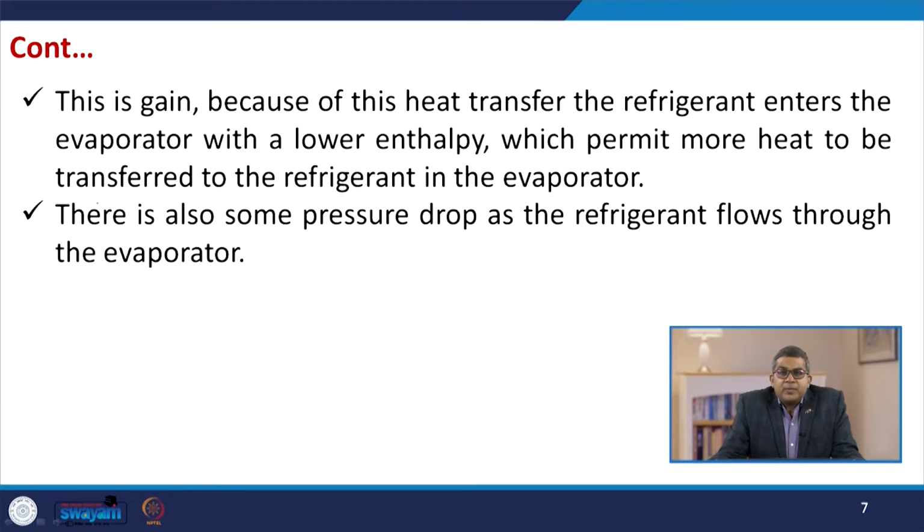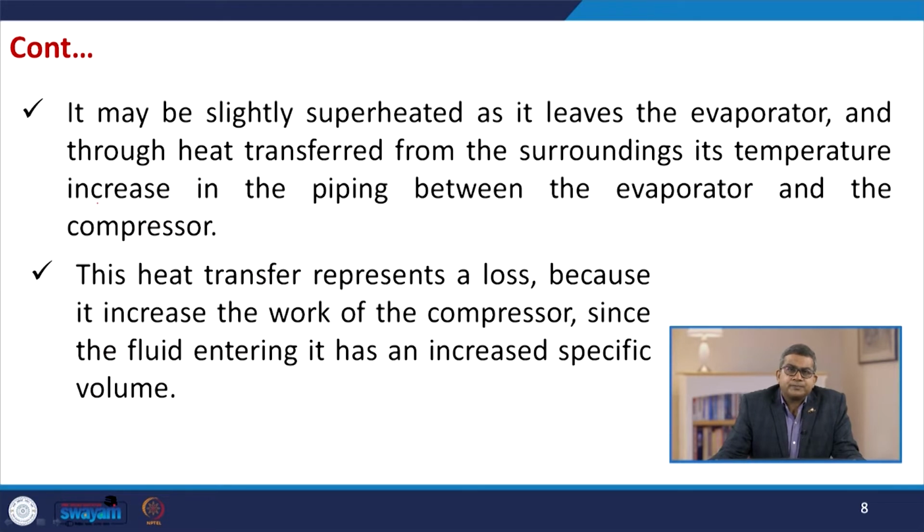Now there is also some pressure drop in the refrigerant flow through the evaporator. It is quite obvious. Now it may be slightly superheated as it leaves the evaporator, and through heat transfer from the surroundings, its temperature increases in the piping between the evaporator and the compressor. Now this heat transfer represents a loss because it increases the work of the compressor, since the fluid entering it has an increased specific volume.